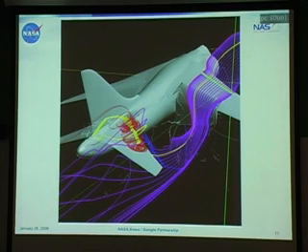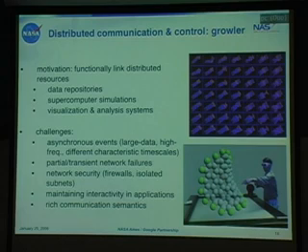Locating that vortex core guides us in the placement of seeding the particles for the particle tracing method here. And in particular, that yellow trajectory that you see coming from upstream, you can see it almost goes under the tail, gets recirculated back over the tail, almost escapes out the back, gets pulled into the vortex, spirals in, and then the red trajectory is actually it leaving the vortex core. You see it's a very, very complex flow. Okay, so that's visualization techniques.